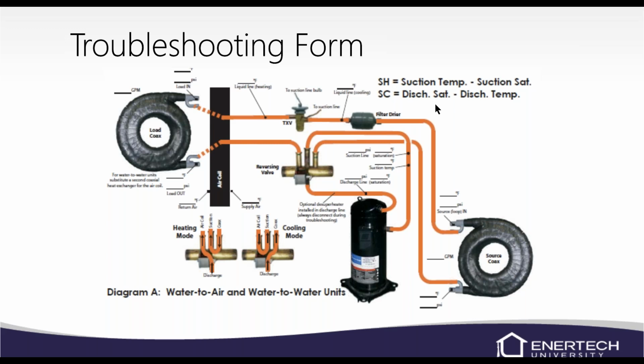Now, if you've made a repair, you've already got your refrigerant gauges on there, so I would go ahead and, of course, check superheat and subcooling. I would also check heat of extraction or rejection, depending on what mode you're in. But always make sure all the components are working first. We've got to make sure everything's turning on before we can expect anything to actually heat or cool properly.